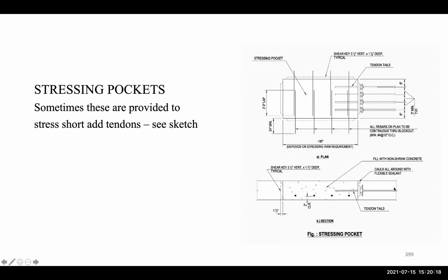So here, you have this part of the PT, you have this part of the PT, you have this part of concrete here, and then you have this. This is the reinforcement here. So this part was left without, of course, the PT. Okay, this part was left without the PT. So that's called the pour strip. And we use that also to apply the pre-stressing of the slab. We saw pictures before about that, and I think I have more coming on this.